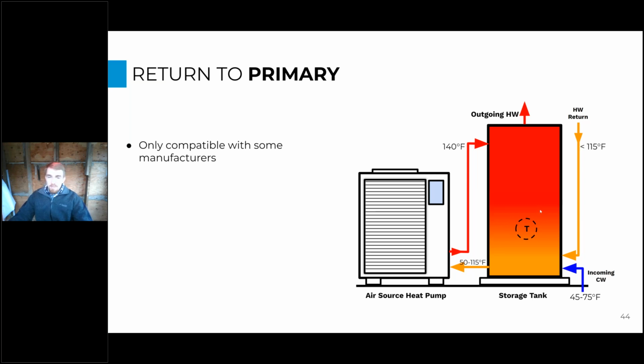Sorry. This is only compatible with some manufacturers because, as I talked about, some manufacturers, especially those using CO2, really don't like that high entering water temperature. So you have to make sure your manufacturer is on board with this strategy if you're going to implement it. And this will usually have a lower first cost because you don't have that dedicated storage tank and dedicated heat pump to handle those temperature maintenance losses.